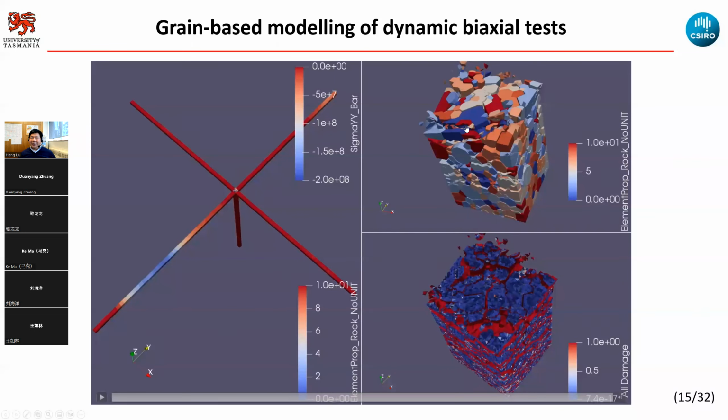So you will see many of that during the failure, which retains the grain shape. That is, I put that in between the grains. I put in the weaker cohesive element there. Yeah, so during the modeling, you can control whether you need to put in the strong or weaker, in the intergranular or in the intragranular cohesive element, when making that model. So that's very flexible.